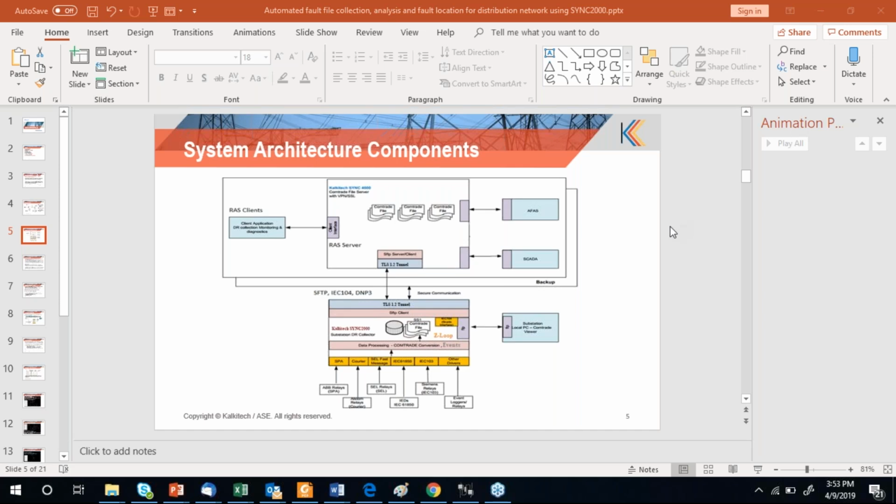Okay, and another question is, from the COMTRADE file, do you also collect the events and expose it? What I was mentioning is the events from the IEDs directly, but this question is on whether from the obtained COMTRADE file we can extract the events. Because there are digital channels associated with the COMTRADE file, whether we can extract the events from the digital channels of the COMTRADE file and expose it as an event file.